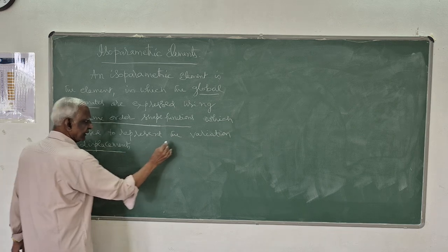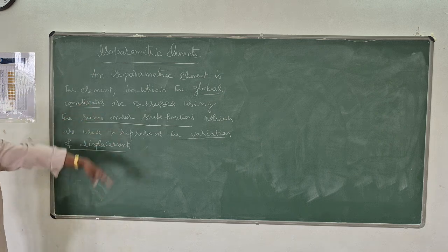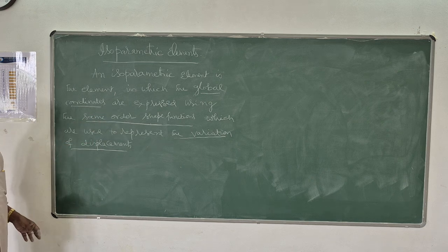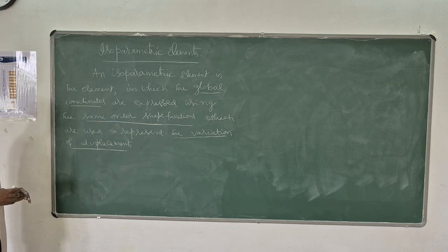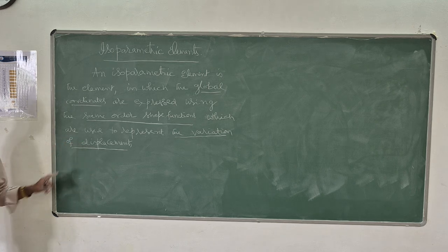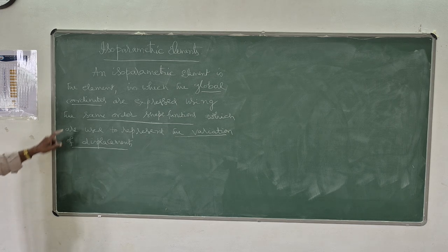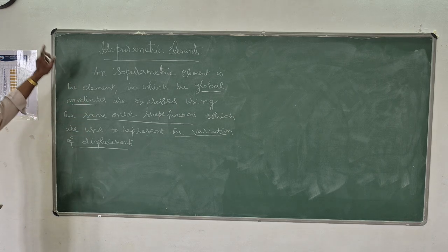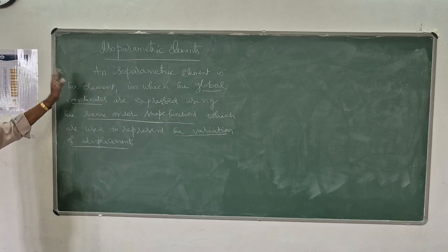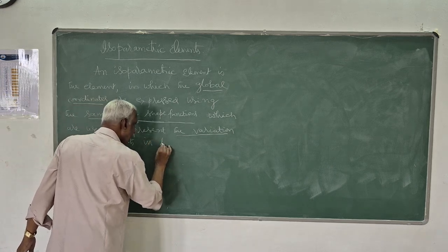For representing the variation of displacements, you have derived the shape functions from first principles as well as the Lagrange shape functions and all the formulas. So those same functions, which you have used mainly to represent the displacement at any point in terms of the nodal displacement, that same shape function you will use to represent the global coordinates.